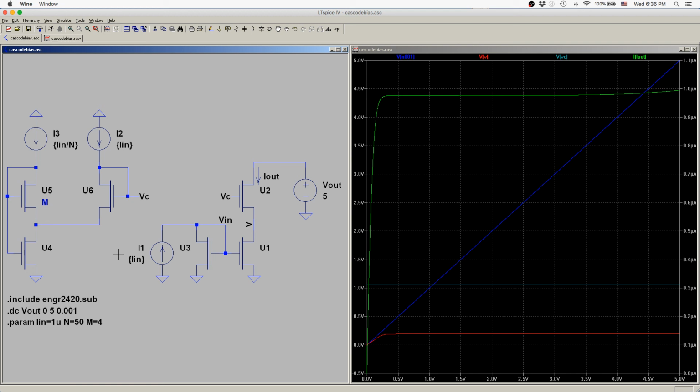So if you're making, for instance, a mirror cascode amplifier, the transistor that you're cascoding could have a current going between, let's say, 0 and the full bias current in the diff pair. So it would be appropriate to set the cascode bias voltage so that it's optimal for the maximum current that could go through as the diff pair switches back and forth, which is the bias current. So you might use a circuit like this to generate the cascode voltages for the NMOS transistor off the bias current for the diff pair.